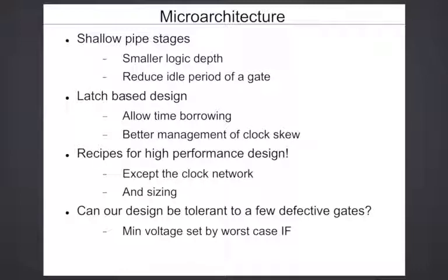Also, the sizing you do for high performance is different from the sizing you do for low power, right? Sizing for high performance follows the formula for minimum delay sizing: you have to size with equal efforts, but that will lead you to large sizes. If you want low power and low energy, you have to keep the sizes small, but you take a hit in the delay.